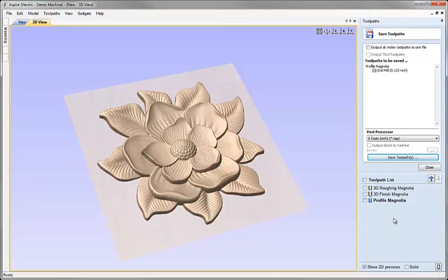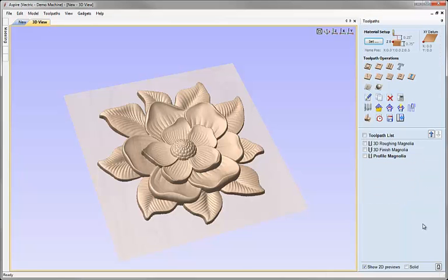And all we'd need to do is make sure on the CNC that as we ran each of those toolpaths, we changed to the appropriate tool and we made sure the XY0 position was consistent and that we reset the Z0 position between each of the toolpaths as well. That way everything should run in the correct place and we should end up with the part that we were looking at in the preview. Let's just go ahead and close the Save Toolpaths menu.